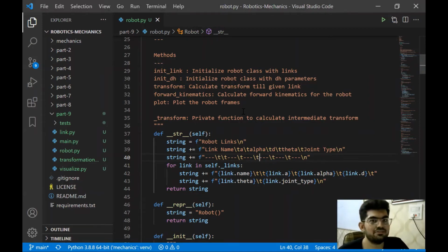I did study inverse kinematics and there are various ways to solve it. The most used way is the optimization one, where we use some deterministic optimization techniques to solve the inverse kinematics. There are also methods like genetic algorithms, which sounded pretty interesting, but we're not going to use them for the time being. It would be really good to code a solution using a genetic algorithm, or GA, but let's not do it for now. Let's just focus on a simple optimization route.